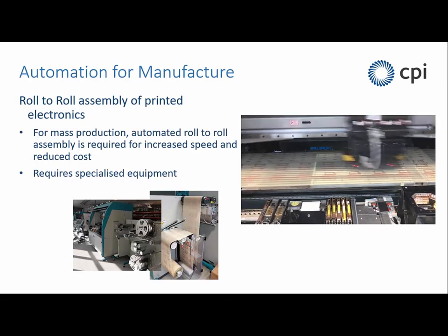So at the end, the continuous roll of substrate is moved along in a stop-start sort of approach. The pick-and-place machine you see there is a conventional machine from Yamaha called an iPulse, and it can pick and place a wide range of components down to 0201, but also very large components, up to even flexible batteries, can be picked and placed with this system.